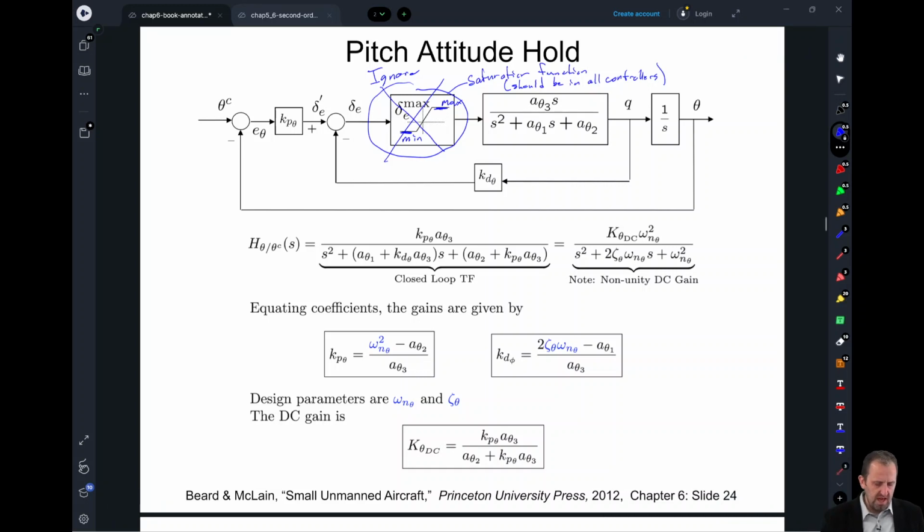And then we have our loop, just like before. We're designing our PD control, and we have a second order system. The one difference with this second order system is that we have this DC gain that we didn't have before. We'll see that that slightly changes what we do from our nominal successive loop closure, but not by a huge degree.